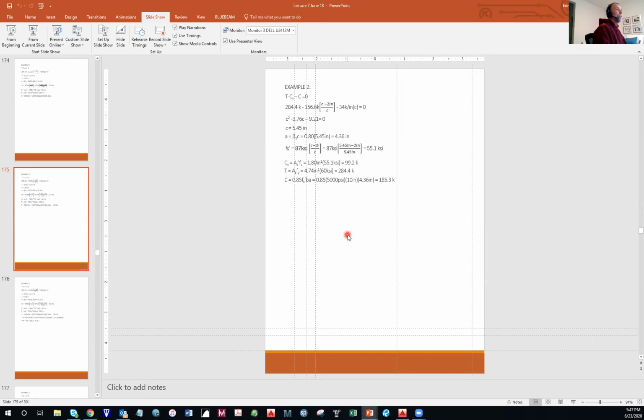So compression steel is kind of broken up into, first of all, 2 classes. You have analysis and you have design. On the analysis side, you can either have your compression steel yields, in which case you already know what Fy is equal to, and then you can just get your 3 forces rather directly, sum your forces, get your nominal moment.